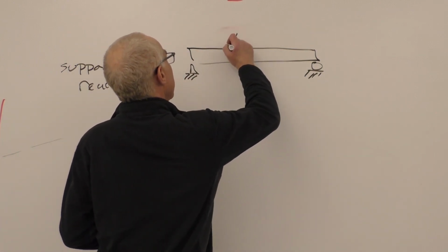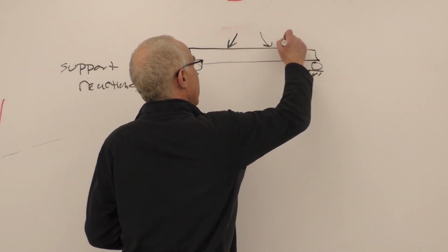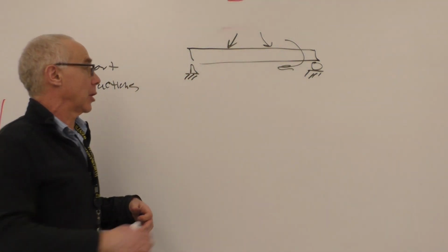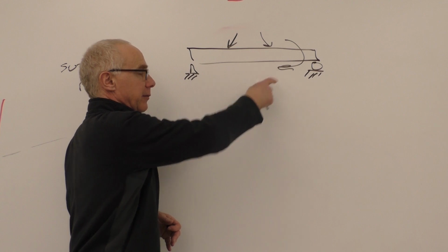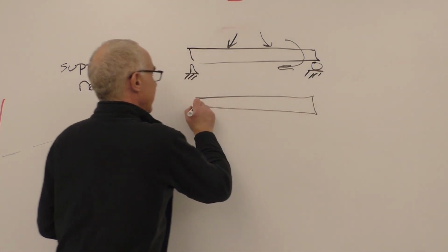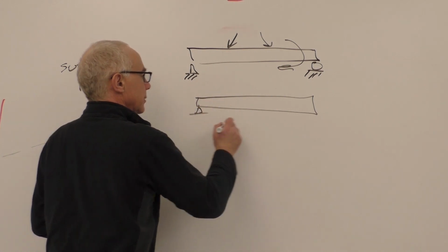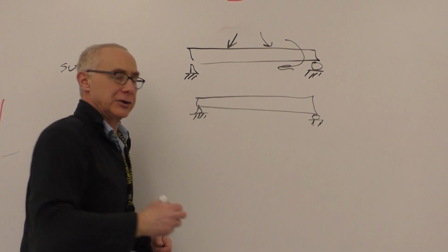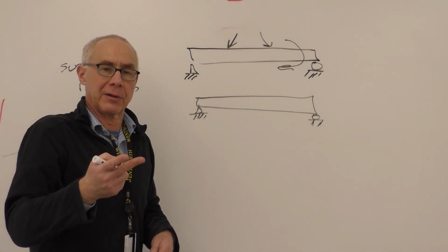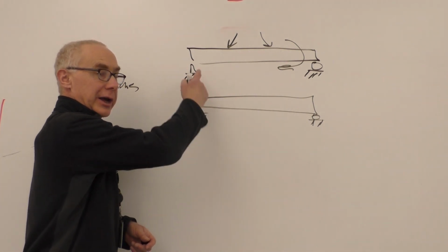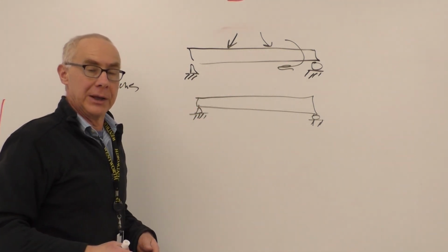So we have, for example, some complex system of forces and moments: two forces and a force couple. You might remember that we were able to simplify it essentially in two steps. The first step is to find a force and moment, which we could do anywhere, but typically we did it at the left edge of the beam.